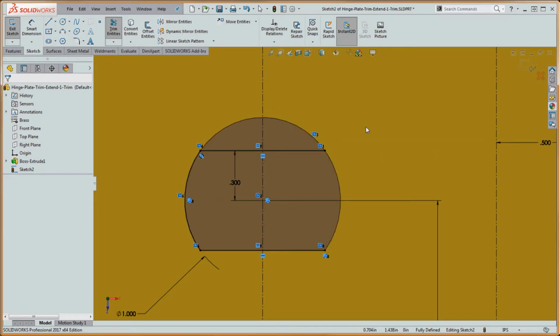One thing you'll notice about that line is that line now all of a sudden became kind of thin, because what we have in here is we have 2 co-radial arcs in here. Line or arc, I think I called it line before, but it's really an arc. We have 2 co-radial arcs in here that are conflicting with each other. One is the primary one when it was sketched first, and then the other one's kind of a little bit thinner line type, and it's sitting in the background. It's okay, but it's not very elegant sometimes to have 2 co-radial arcs that have a common endpoint here.